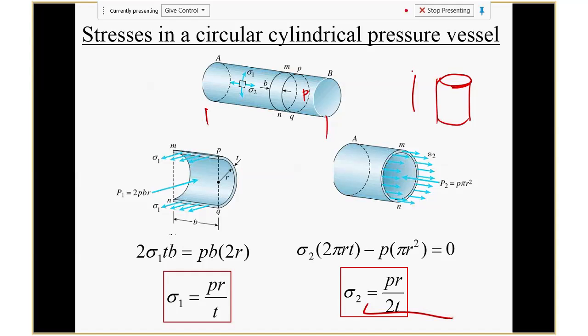So when you're calculating the stress in the longitudinal direction, the end could really be any shape. Yes, it could be anything. When you have a container, the shape of the end doesn't matter, because far away from the end you have an equivalent: a pressure acting on a surface of area pi r squared, pulling this tube longitudinally. The shape only affects the local stress. In the middle part, it doesn't matter anymore.